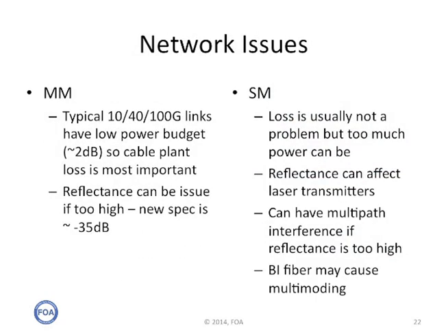Single mode and multimode fibers have different problems when used in data centers. Multimode links have bandwidth distance limitations due to modal dispersion. The derating factors for dispersion on multimode fiber can limit power budgets to as low as 2 dB, not the 5 to 6 dB you would figure from looking at the transmitter output and receiver input levels. Single mode links are capable of longer runs, so loss is not an issue, unless the loss is too low and attenuators are needed at the single mode receivers because of overloading.